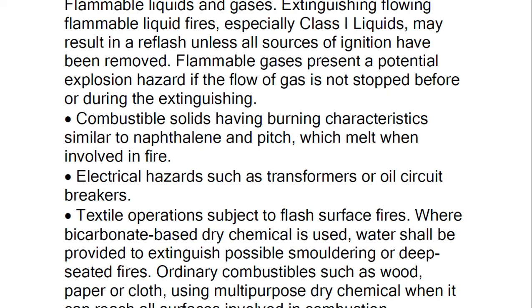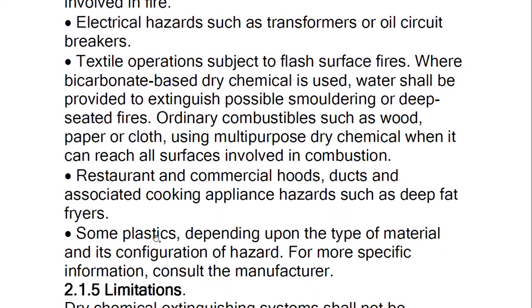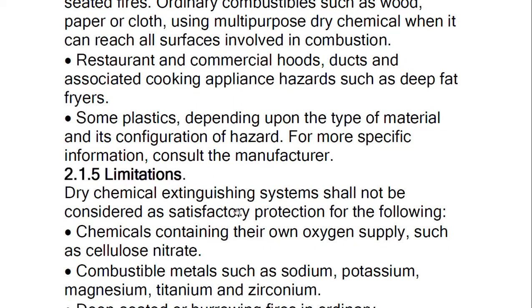Textile operations subject to flash surface fire, where bicarbonate-based dry chemical is used. Water shall be provided to extinguish possible smoldering or deep-seated fire. Ordinary combustibles such as wood, paper or clothes: we are using it on all these fires described here. Restaurant and commercial hoods, ducts and associated cooking appliance hazards such as deep fat fryers. Some plastics, depending upon the type of material and its configuration of hazard. For more specific information, we consult the manufacturer.